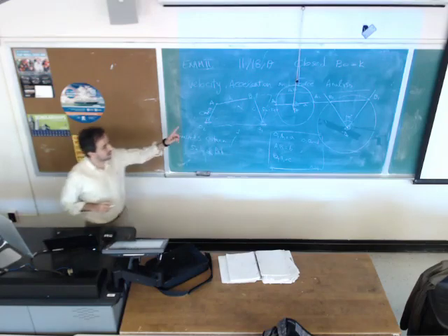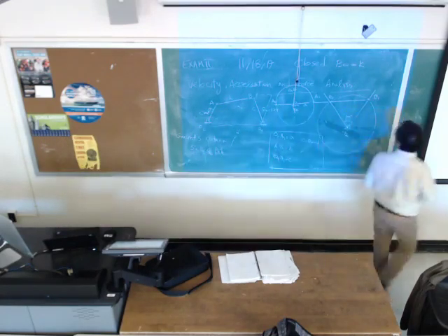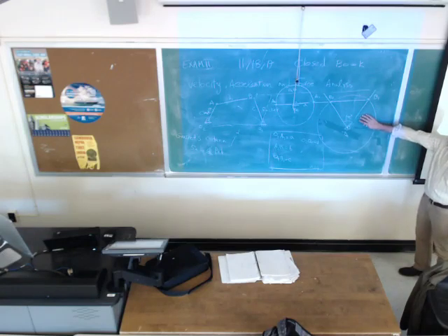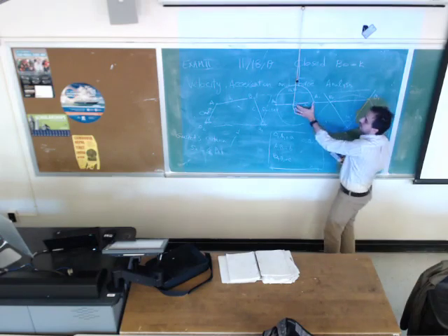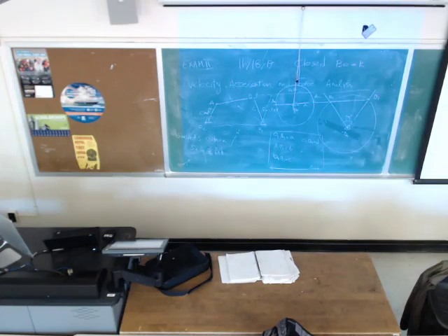Good. So let me go deeper on this. You design the mechanism, and you measure it. The link A, which is our crank, is O2 A1. B is A1 B1, or A2 B2, they are the same. C is going to be O4 B1, or O4 B2, and D will be O2 O4. And you check them, and it's satisfying the crank rocker criteria.